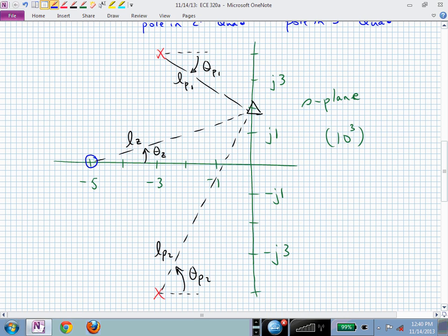Each of these singularities presents itself with different magnitude contributions and angle contributions. I picked something that was less than j4000 so that the angle of that upper pole would be negative. And you need to keep track of the signs of those angles. That's the reason I picked 2000. There was no justification for that in the notes or this presentation so far. Does that help clear things up? So 2000 I simply grabbed out of thin air.